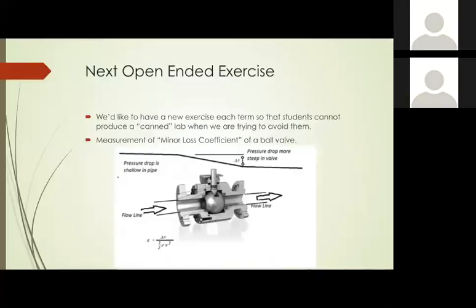There's a little bit of turbulence, there might be some flow separation, there might be some recirculating flows in there, and you suddenly get a larger pressure drop, and then the slow pressure drop continues. That small pressure drop right there, we divide by the kinetic energy density in the fluid flow to make it non-dimensional, and that means that engineers can apply it to different fluids, they can apply it at different velocities and so forth, but that becomes our coefficient then.